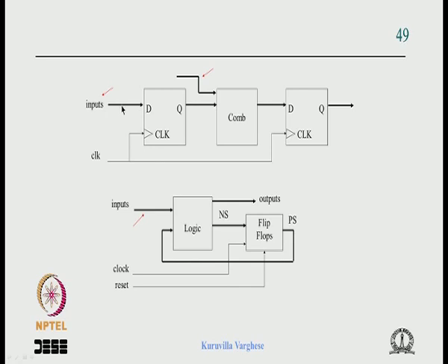That movement is probably driven by a motor which has got nothing to do with this clock. So that process has no relation to the phase of the clock here, so it can violate the setup time at this input. Whenever there are inputs which are not synchronous to the clock you are clocking the registers with, they can cause metastability in the respective register.